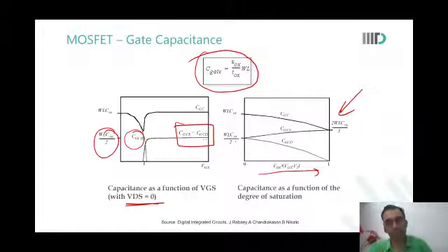And the second question is, in this graph we are seeing the components CGS, CGD, and CG bulk. But when we studied the MOS capacitance, we were only looking at the gate to bulk, because there was no source or drain there. Yet here the gate to bulk capacitance keeps decreasing and vanishes. It decreases for a MOS capacitance also, no? That is where we end up with the depletion region, where we go to WD max and say this is the minimum capacitance you would have.